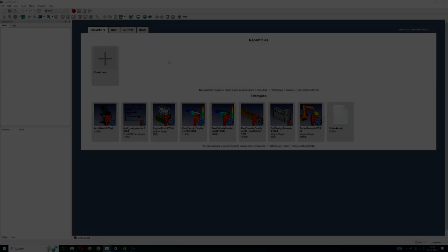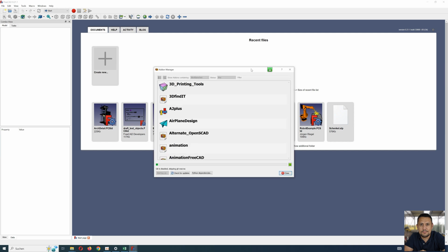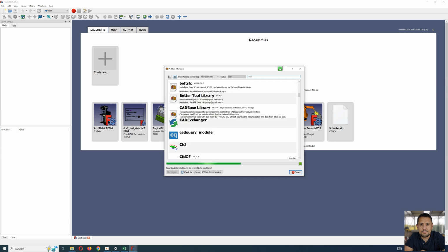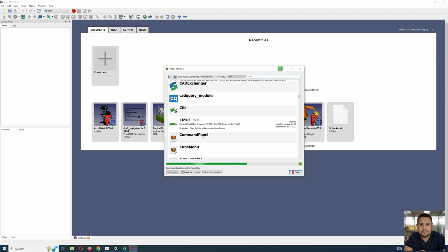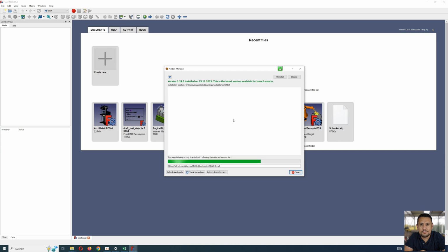First step, install FreeCAD. And after this you can start the add-on manager for external workbenches. Here is CfdOF. It is already installed on mine. I only show the necessary steps.